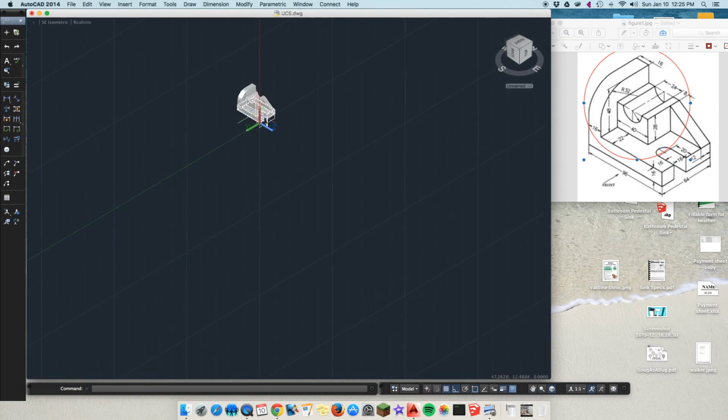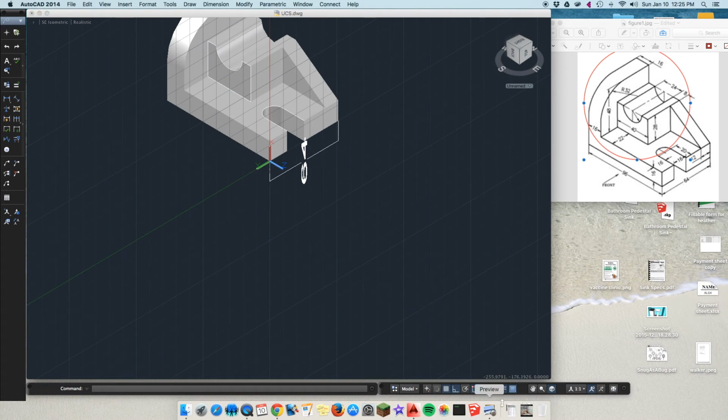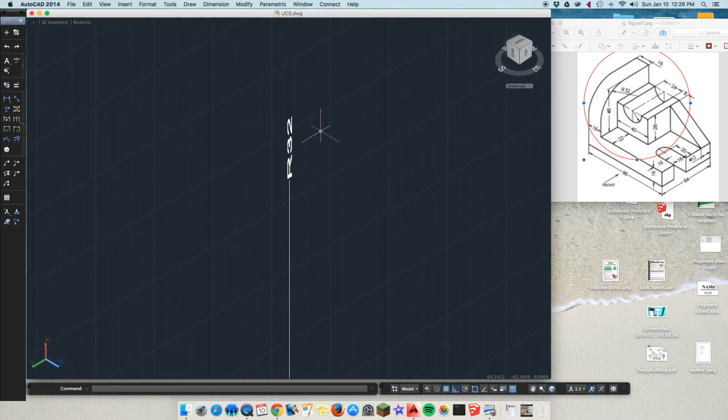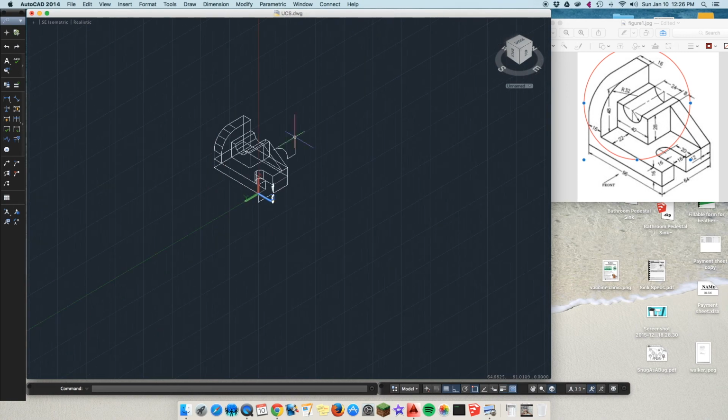I would like you to play with the dimension style settings until you can get it working. The radius one, by the way, if you click and hold on the linear dimension tool, there's one called radius, and all you have to do is click this edge, and then the radius should show up. Select an arc or a circle, and the radius should show up. It's doing it on the front side here because of where I have my UCS, but if I zoom way in, it should tell me radius 32. Make sure you post your work, and good luck. Thanks.